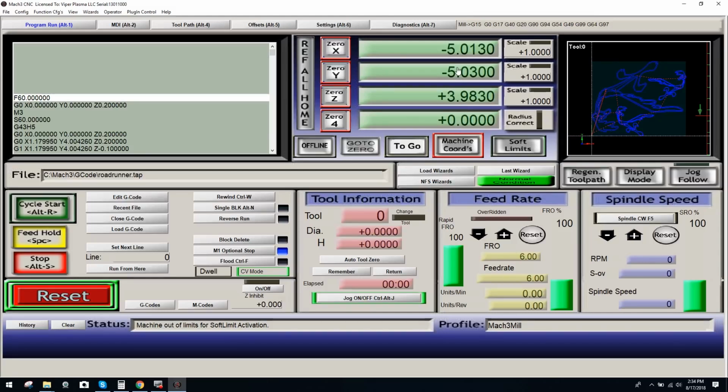You're still this distance away from your end stop, okay? When we really aren't, we want to say this is our actual new home position. So to actually define our starting home position, now is the time to hit ref all home, and then you will find that the 0x, 0y, and 0z axis boxes will become illuminated green. Also, your integers have now changed.